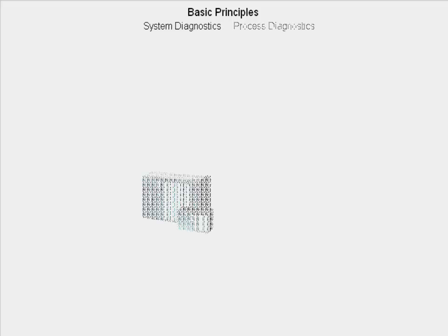The diagnosis of a fault is normally based on which components of a system or machine are diagnosed. We therefore differentiate between two types of diagnostics: system diagnostics and process diagnostics. System diagnostics covers the monitoring functions that concern the correct functioning of the components in the automation system, which includes everything from S7 CPUs and function modules to network components and intelligent sensor interfaces.